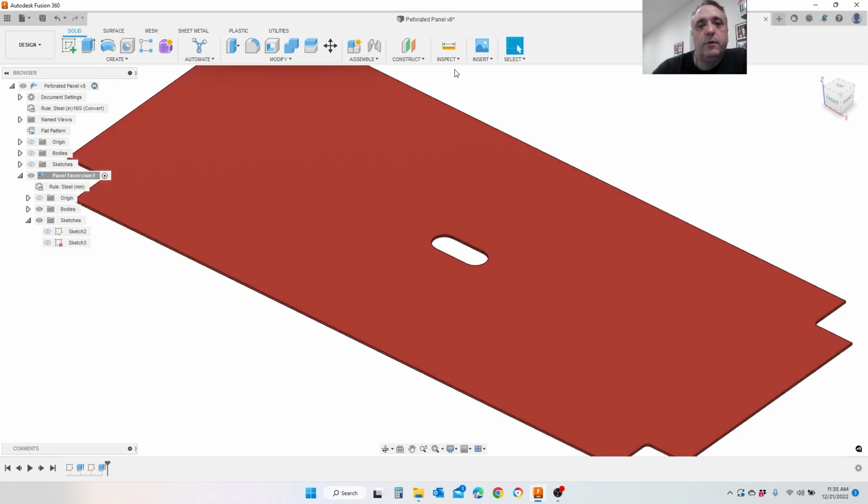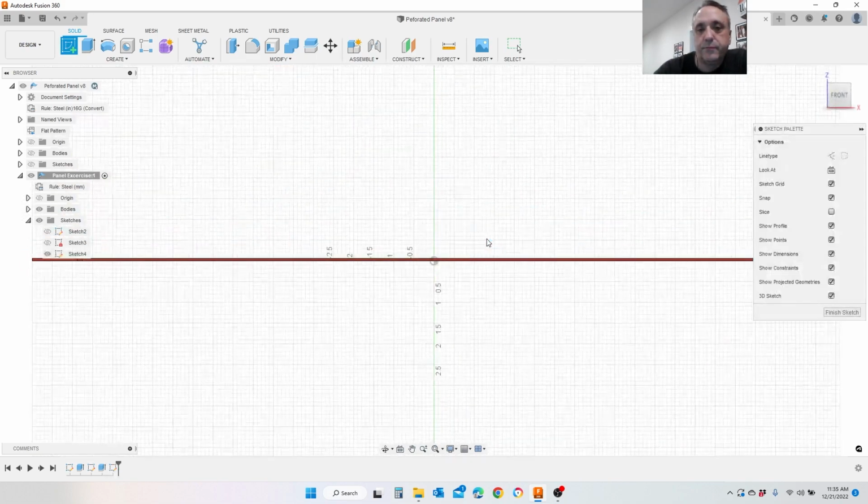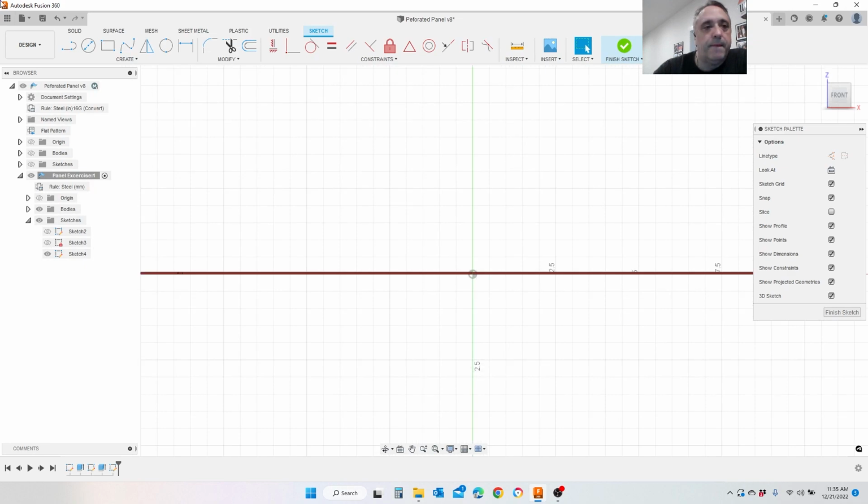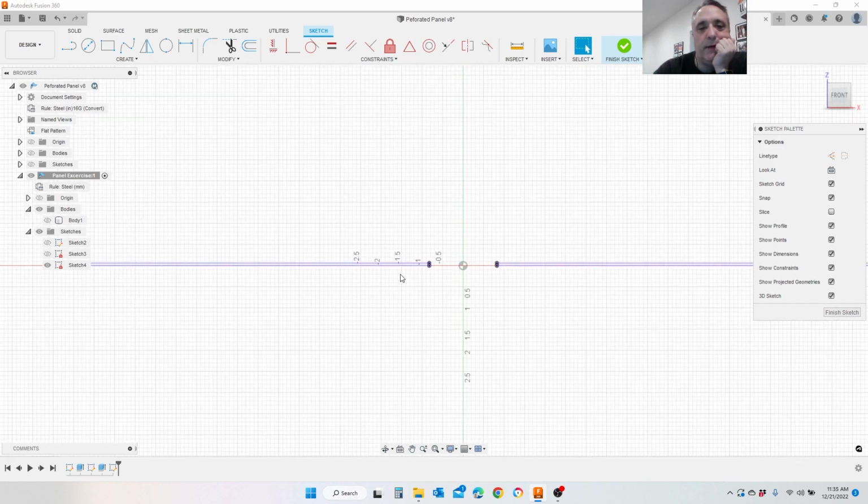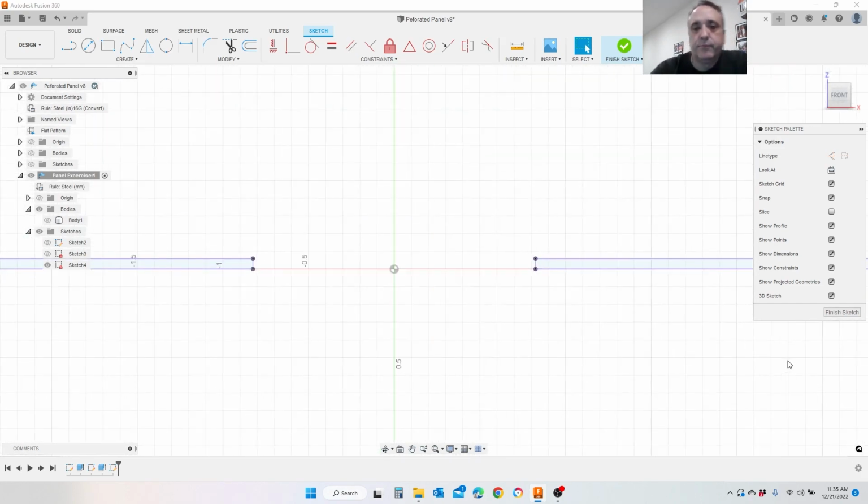So we are going to do a new sketch, and we're going to do it right in the middle. And then you want to do project, include, intersect. Pick the body that we want. It's right here. We could select it, or you could select it over here. And it's going to create those lines. Let's turn the body off. You can see now we have reference lines. Let's turn on the axis, just so we can see the origin axis.